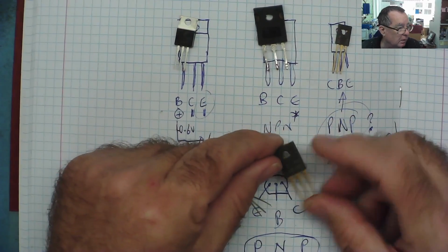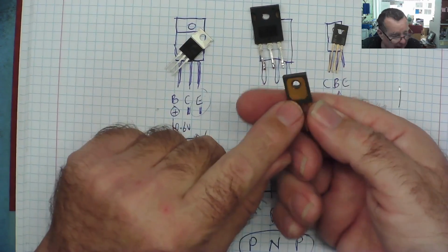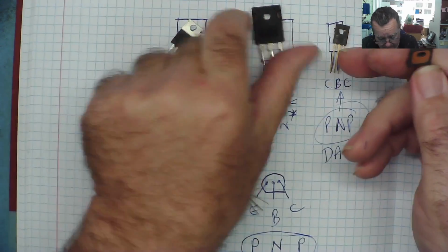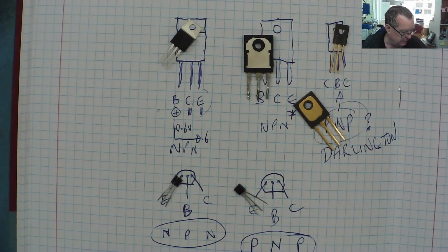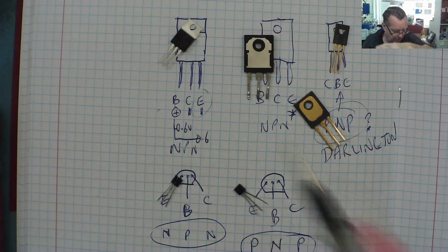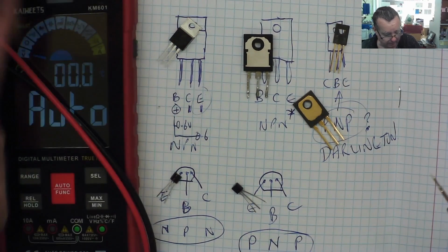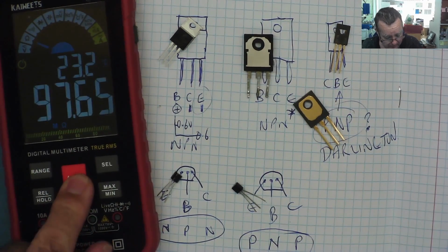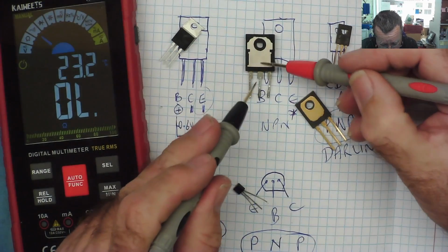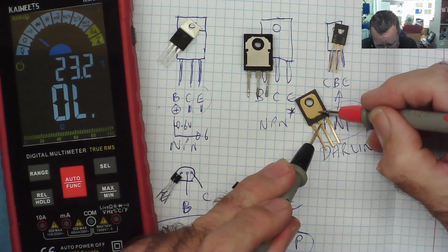It is another one similar to these. If you find transistors with a metal tab on the back, almost always you'll find that metal tab is actually connected to the collector, which is the middle pin. We can just check this. We'll put the meter on here and go to continuity range and have a look. So this metal tab is connected to the middle pin, okay,